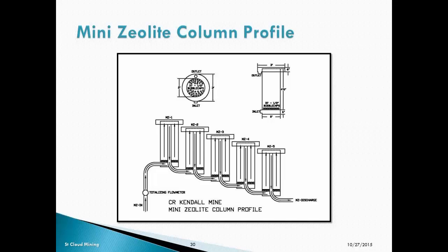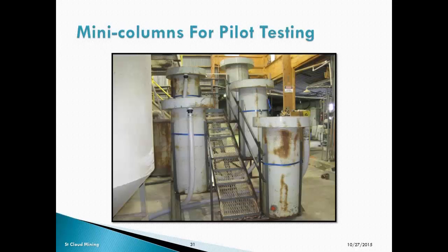So if you had debris and leaves and gravel or about anything that could get into that water, because there were real changes through the year of how much water flow came through and what kind of sediment load it could carry, that just simply got trapped in the zeolite upflow system, but did not impact the ability of the zeolite to work well. And this is the pilot system that was originally put in place at the Sierra Kindle mine.